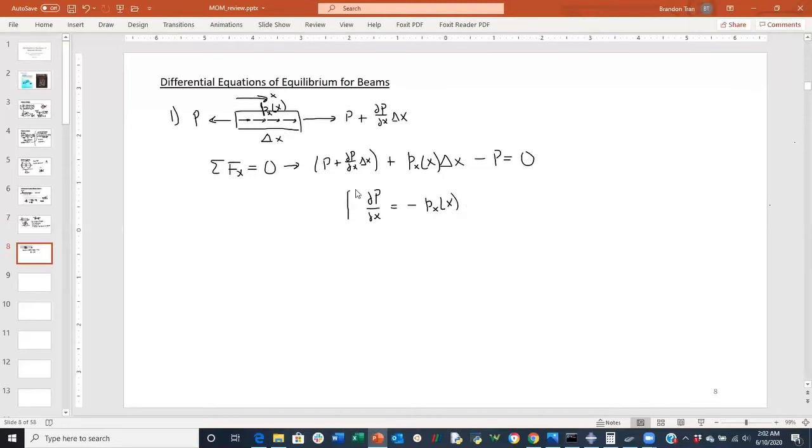Okay, so this is a very effective equation. Essentially, if you have a distributed normal load, you can relate it simply to a singular point concentration normal load by just carrying out this integral here. And if it looks fairly obvious, this integral here would essentially be delta x if you move the partial x over here. So this is our first equation.